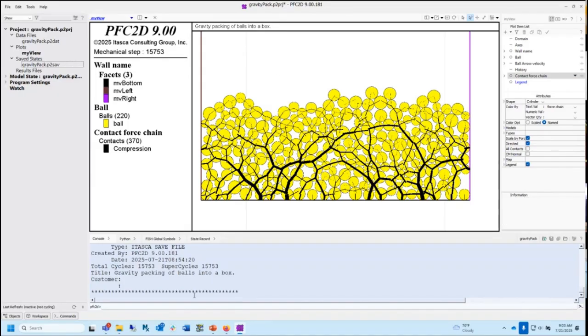But in PFC, we can actually create a region, and in that region, we can measure directly the porosity, because the porosity is the volume of voids over the volume of the region. So in PFC, we can define these regions. The regions are going to be disc-shaped, circle-shaped in 2D, and they're called measurement regions. You can compute different average quantities over those regions.